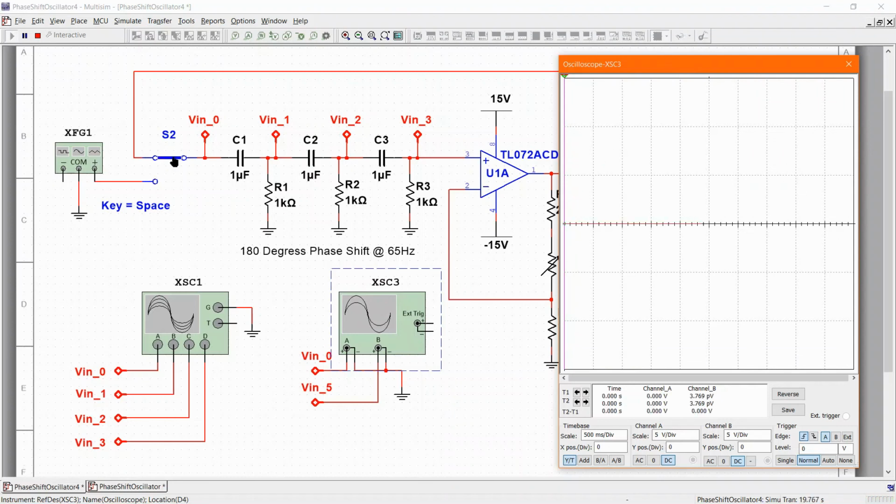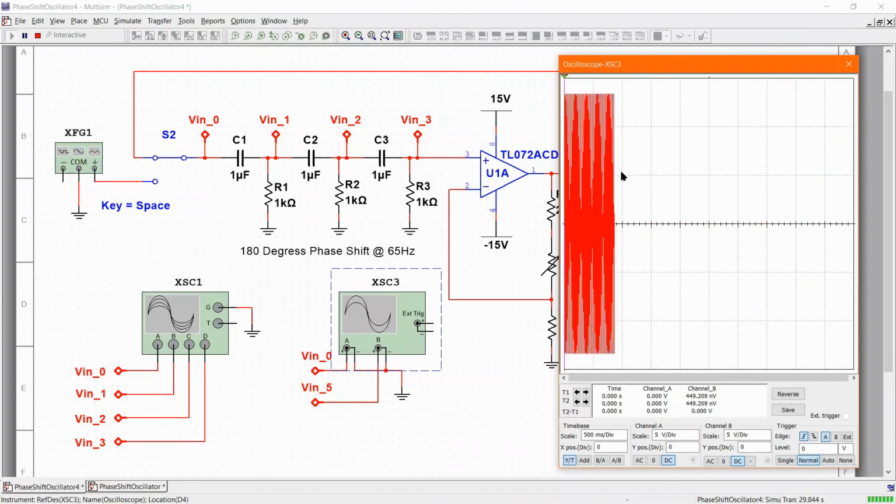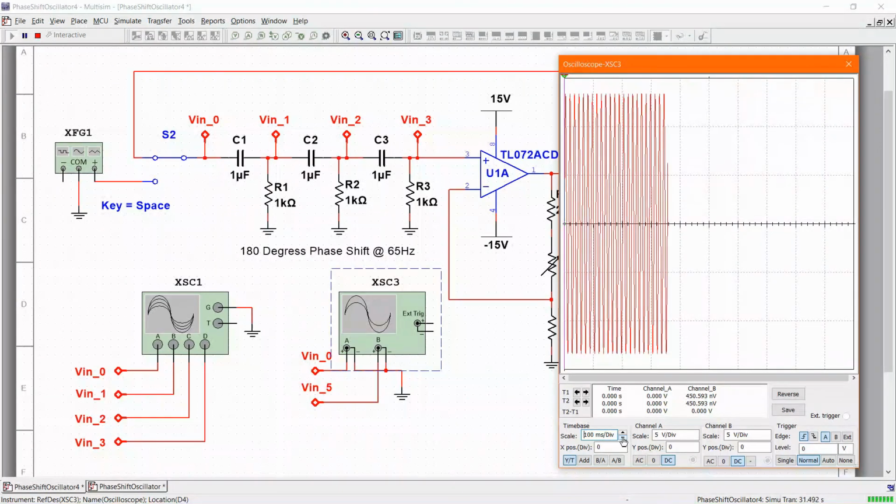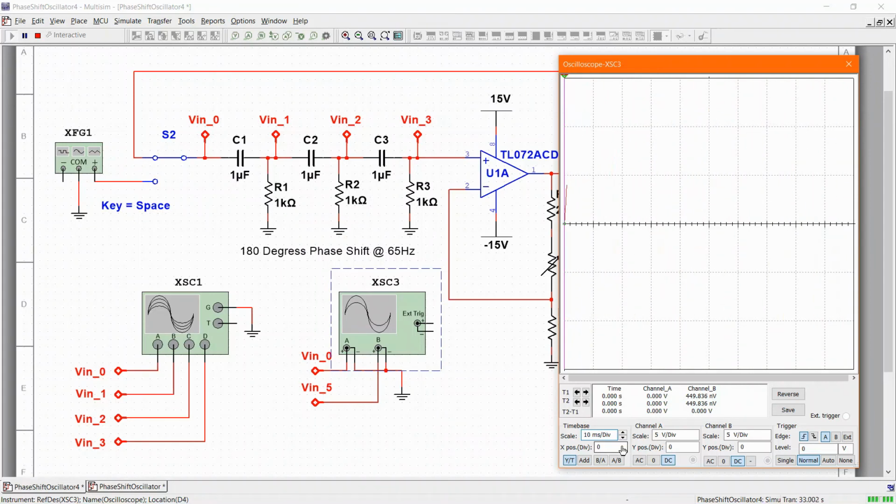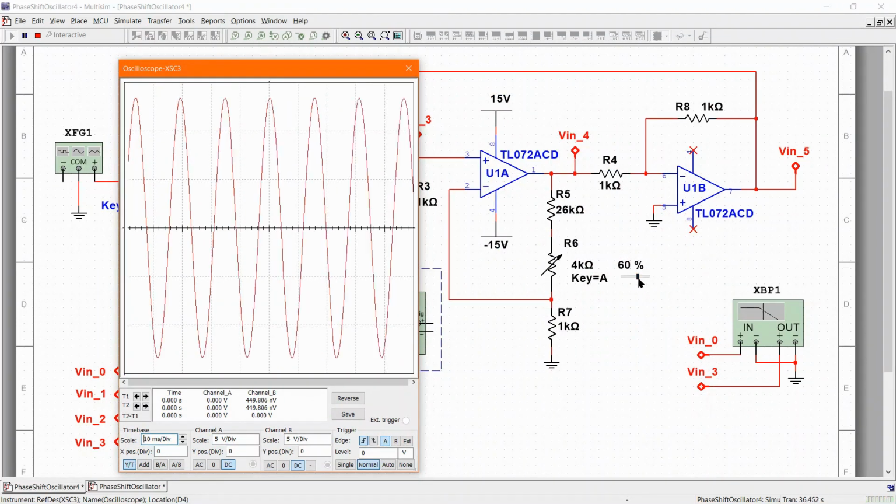I'm going to come over here and I'm just going to hit this switch really quick and toggle it over here to the generator. And then you can see the oscillation is off and running, and it's slowly increasing until we get full amplitude. So there you go. A little bit of random noise will get the oscillation going. So to do that, you might need a gain that's like 1.01 just to make sure that it gets up